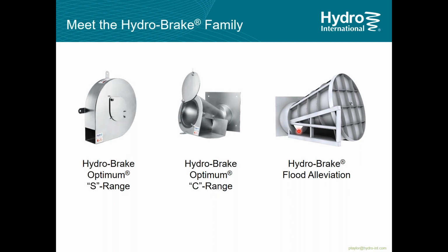The main difference between the S and the C is that the S-type valves have a submerged sump, where the C-type valves have a matched level invert, so they drain down the upstream structure completely, and the S-type will actually retain a wet sump.